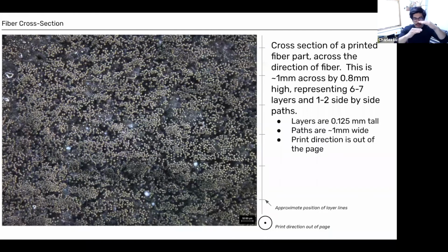If you imagine all these short fibers pushing, not against each other, but having to push through a kind of soft material, it's like getting dampened each time you're transferring a load. So with the continuous fibers, you're seeing a lot less transfer through the matrix polymer. You're seeing the transfer happen from fiber to fiber. And that is really what's going to make it feel a lot stiffer as an end part, and also what is going to give it its elevated strength.